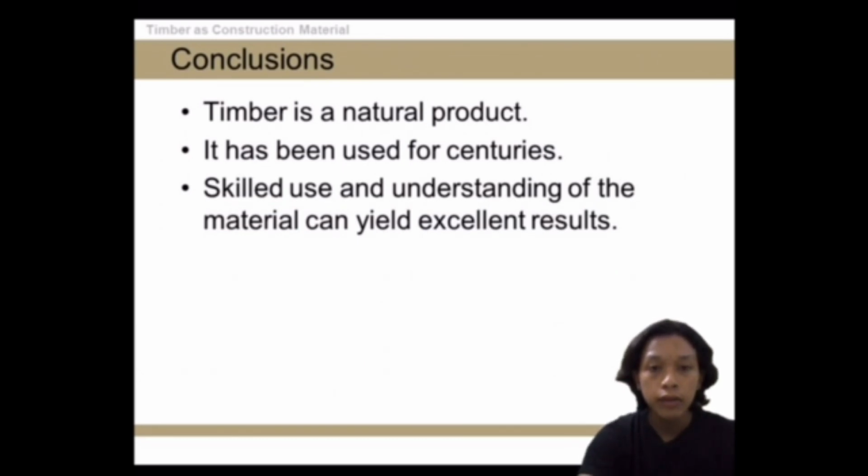Against this background, unless the component required is going to be used in a design for a wet environment, it is fundamental that wood must be dried to a target moisture content level before use. This will ensure minimal and restrained movement.